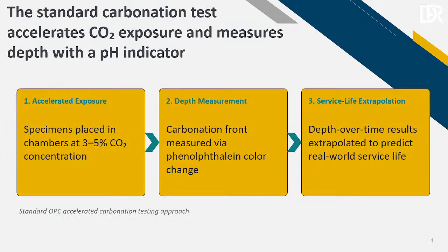The normal thing for carbonation when you're working with concrete is that you put your specimen in a chamber at 3 to 5% CO2 for a few weeks, and then you run the test and you use your available models to see how they work with the actual data in the field. You have a sense of the carbonation value and how much the carbon has penetrated into the depth.